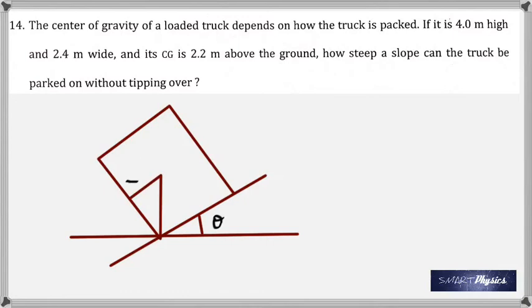To find how much it can be tipped over to a maximum, you have to draw a vertical line from the center of gravity straight down, and if it falls just inside the base, like in this, remember this is the base, so this vertical line from the center of gravity is just inside the base, so it will not tip over. That's a boundary condition. A little bit more to the side, it will go down. You won't get it back. So I've drawn the limiting condition here.